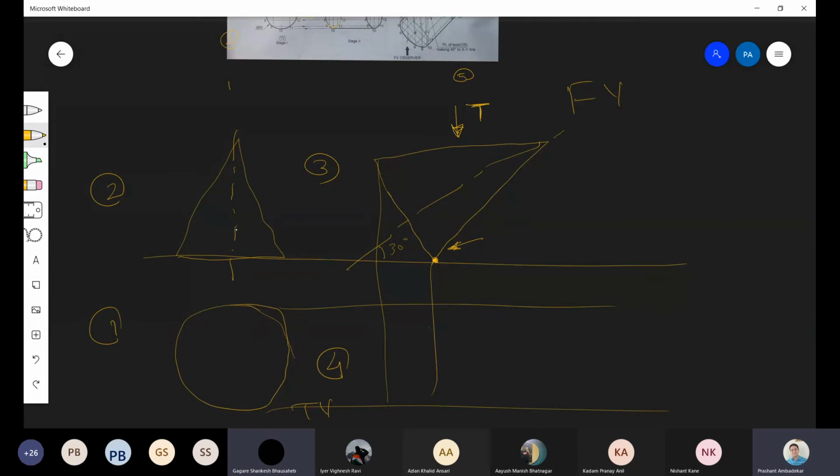No sir, it is hidden. Other students answer. No, sir. So as we cannot see this point, half of the ellipse will be dotted. So half of the ellipse here will be dotted and the remaining half will be drawn by a continuous line. And then I project this here and the axis from here like this.